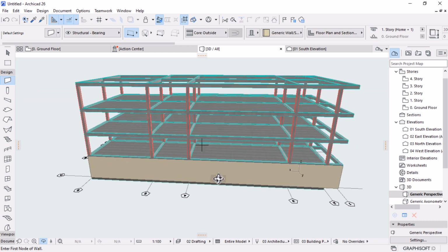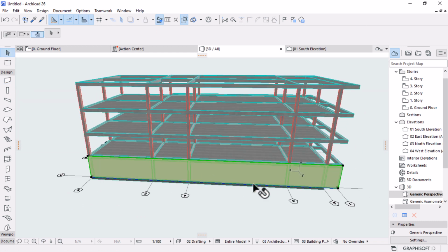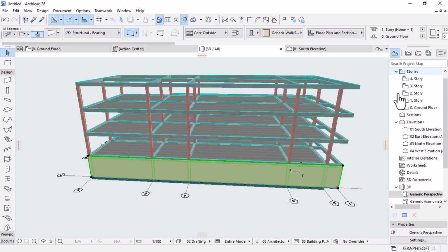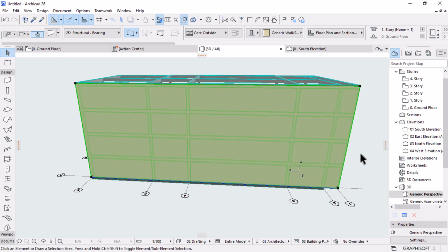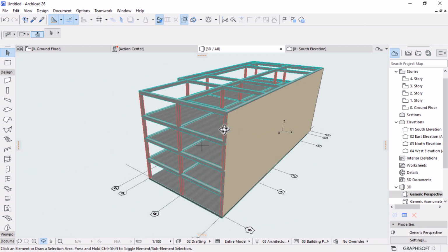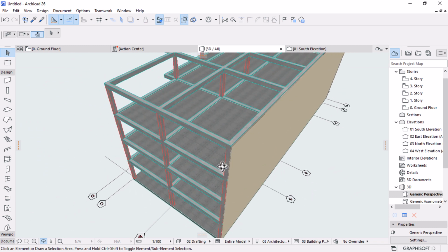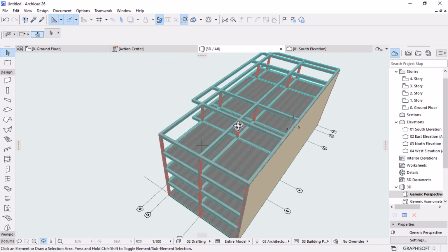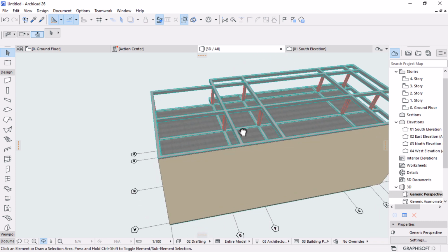Okay, this wall needs to be multiplied across. I could copy this wall into all these floors, but that will take ages, so I can just stretch this wall all the way up like that. And because I know this part is going to be roofed separately and it's going to be higher than that side, what I need to do is trim this wall into 2 parts.